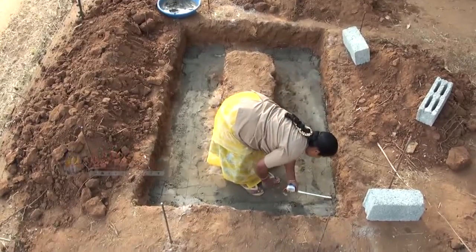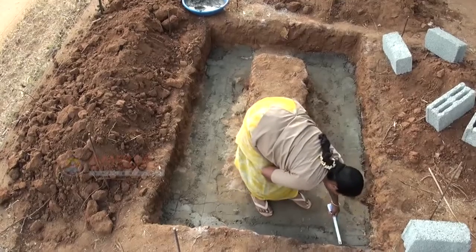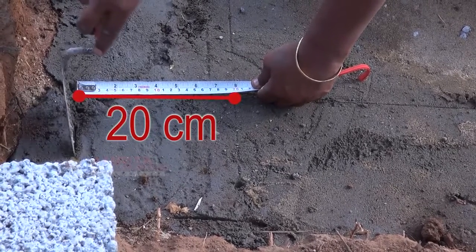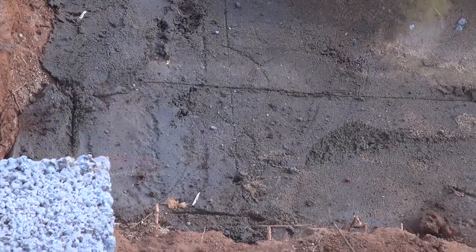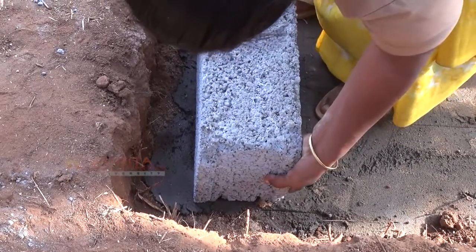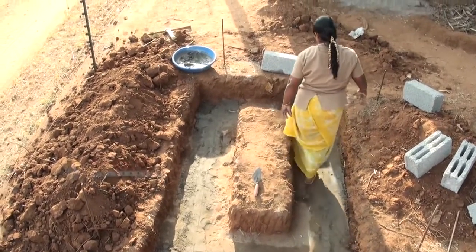From one corner of the central line rectangle, measure and mark 20 centimeters outwards to the top and left. Now repeat the same procedure on all corners. Place the first hollow block from the top mark that we just made. Place another hollow block on the opposite end.